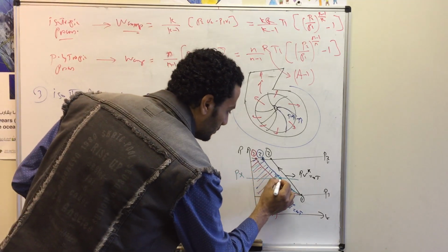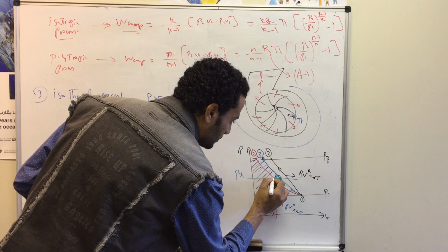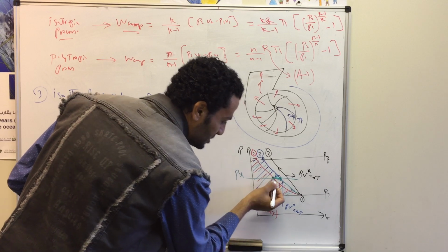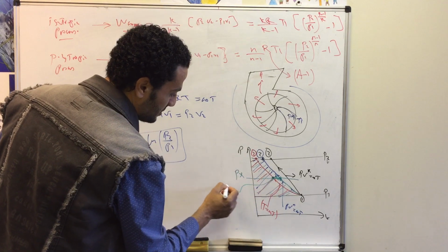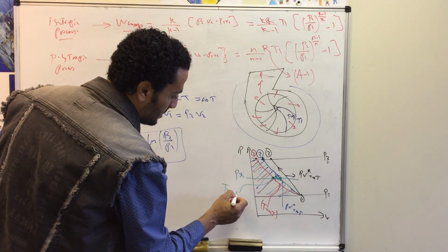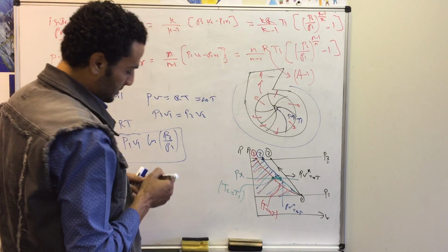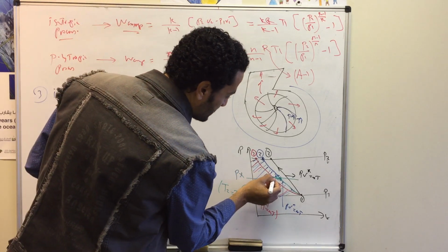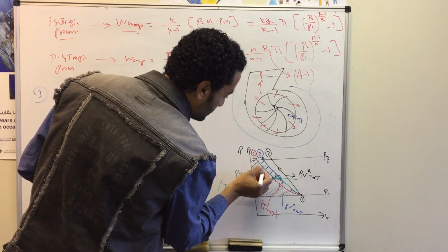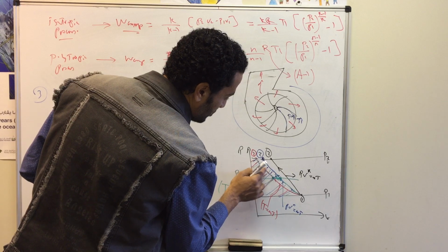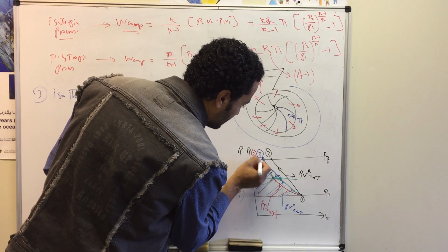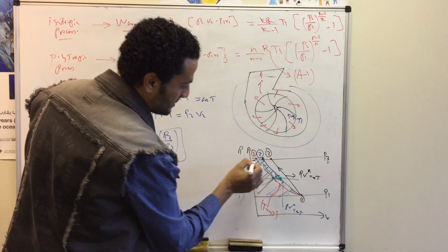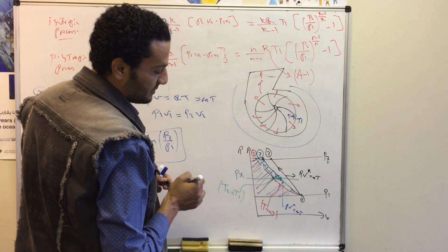Then we do a cooling process, which is called intercooling. I will cool down until I reach the line of isothermal temperature. So in this case, the temperature T2 will be the same as T1. Then we can complete the compression process following another polytropic line. So it will be something like this. Then we can reach a final point here.